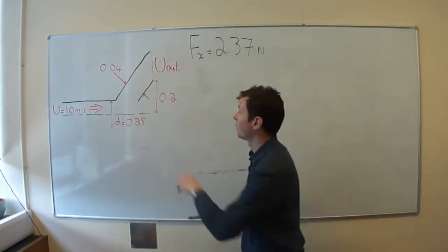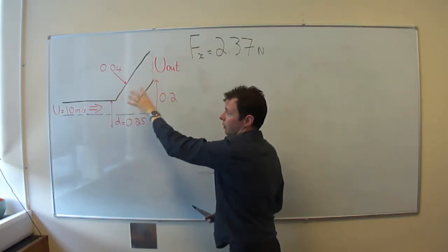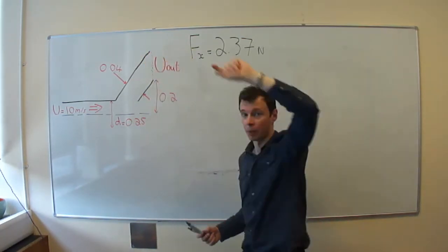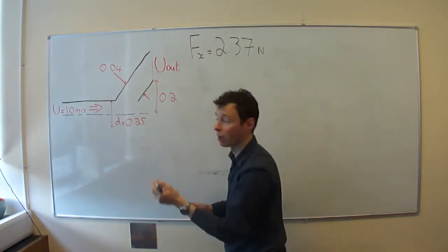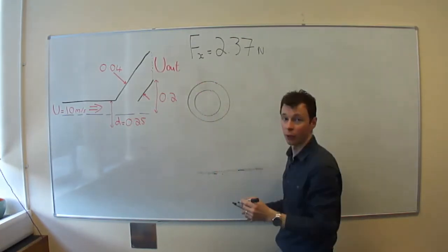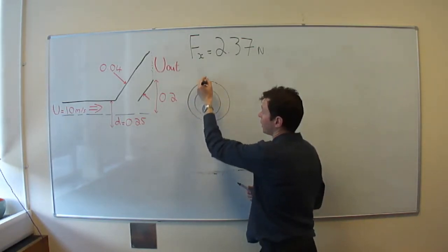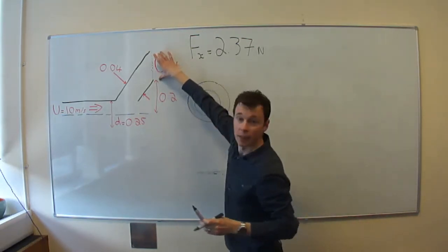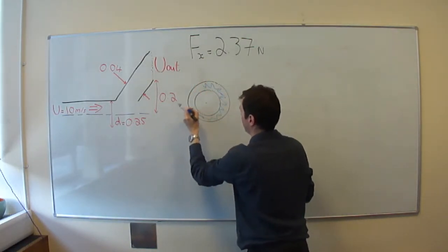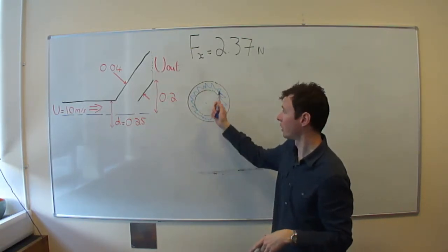Right, to work out the area out, again we have a sort of annular band. Imagine this geometry is rotated around an axis, so we have circular elements sweeping around. Effectively two circles, one away from the other. So if we're looking end on, this is our inner circle, radius of 0.2, and the outer circle is going to be 0.2 plus this distance here. And we're working out that area in there. You can do it 3 or 4 different ways. I always prefer just to work out the areas and take one away from the other.